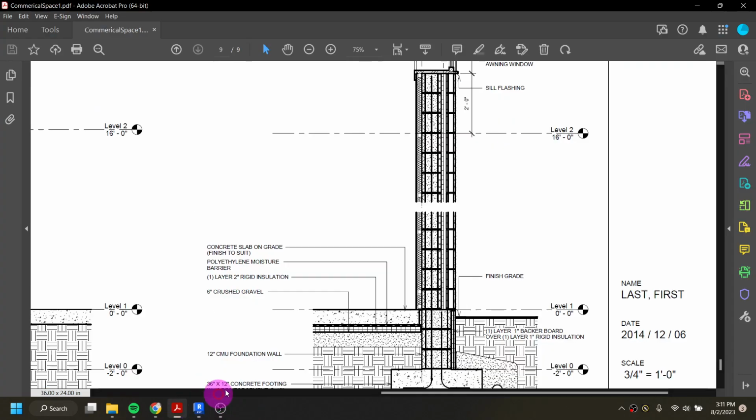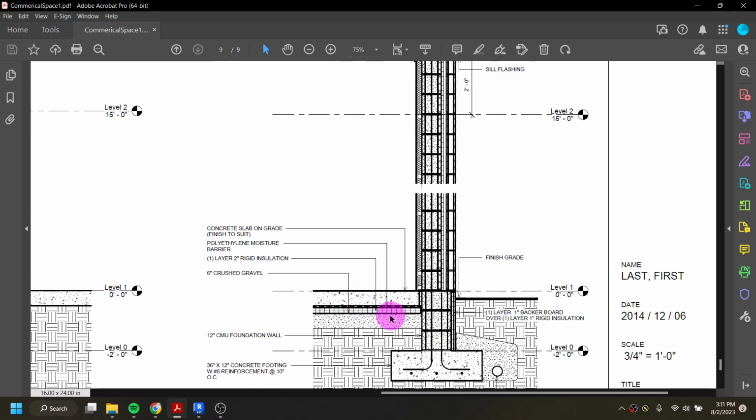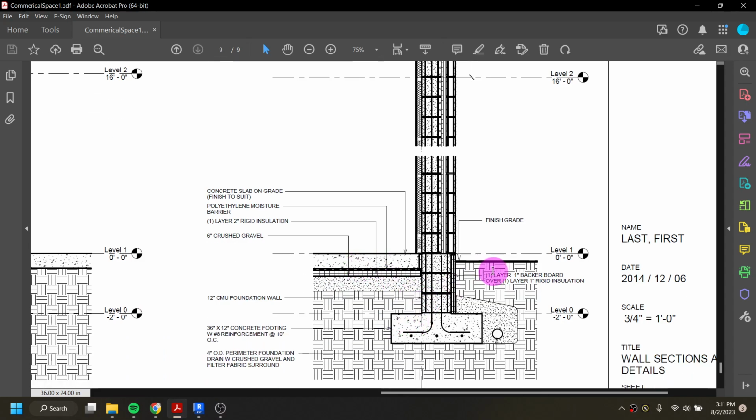So one thing you'll notice is that I have this ground line is very, very heavy. And that's just something of being able to kind of add in additions to it. So we'll start our filled regions with our CMUs. We are going to fill them with the hatch pattern sand to make it a little bit easier to work with.